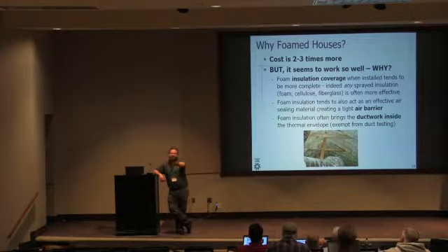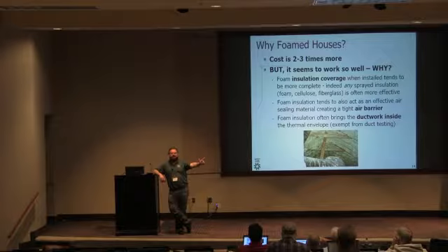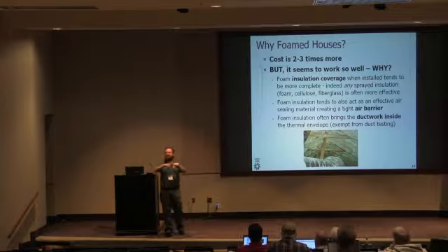You can do any installation correctly, but fiberglass in particular is the cheapest product, but it requires the most labor and the most attention to detail to be done properly. But what happens? You buy the cheapest product and you pair it with the cheapest labor source, and you get poor quality installation. And that's what's going on in the real world. And that's the three big things we found from the Energy Code field study we did: installation sucks.